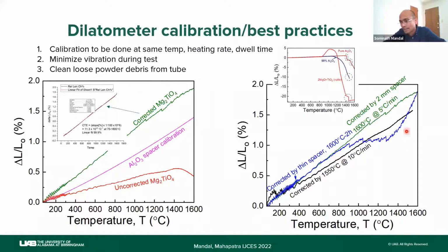When you have an extra dwell time, but the same maximum temperature and same heating rate, but a different spacer, that also changes the values. So you have to use the same spacer. You have to be very particular in how you measure your sample, and then you have to put it on a polymer stand, a damp proof, vibration proof stand, which prevents these vibration induced defects.